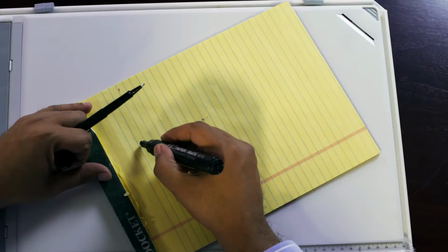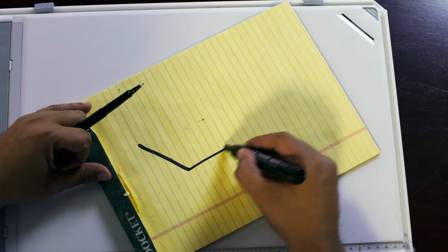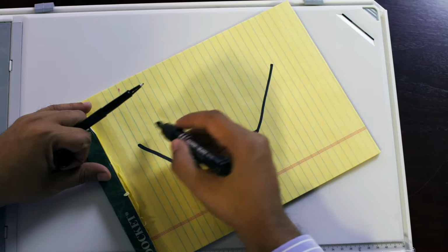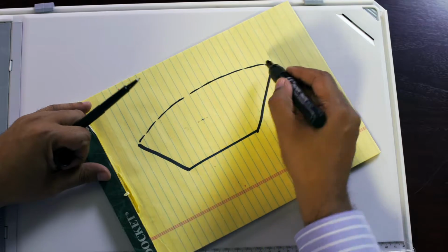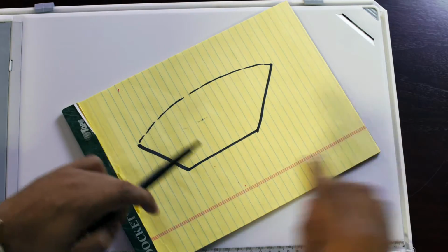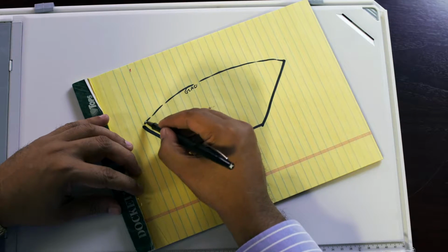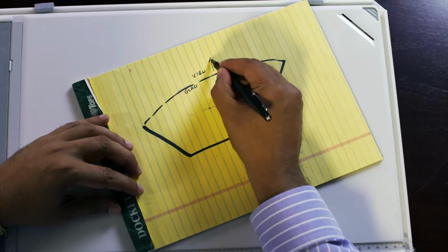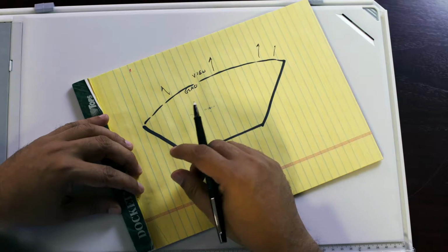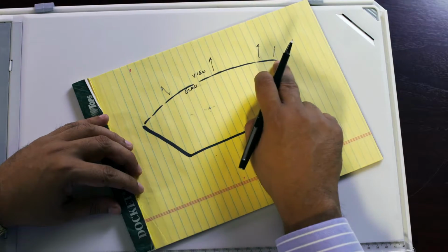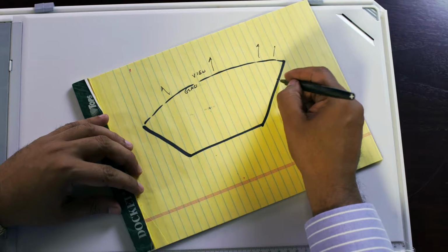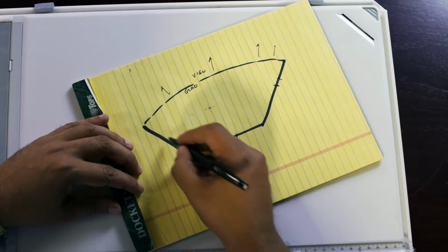Let's say you're designing a floor plan, and I'm just going to make this very simple. You design a floor plan, it's not rectangular, shaped in kind of an odd fashion, where this is all glass, because you have a spectacular view here. You're up in the Hollywood Hills or on the top of a mountain. So you design a floor plan which has all glass, and then you have walls over here. We'll put a couple doors in here, okay, to get in and out of the space. The problem with this design is that we're missing an entire load path where this glass is.